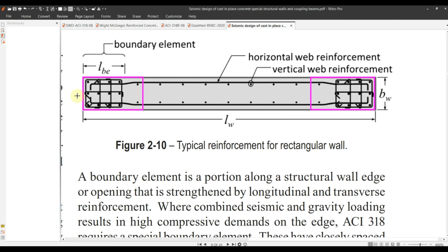We can provide some dense reinforcement here at the rate of 3 inches center to center, or say, for example, 4 inches, or maybe we can use 25 here at the rate of, say, 4 inches, and maybe we can use some central reinforcement like this. And if the width of your wall is pretty wide, then you can use 2 rows of additional reinforcement inside here, right?